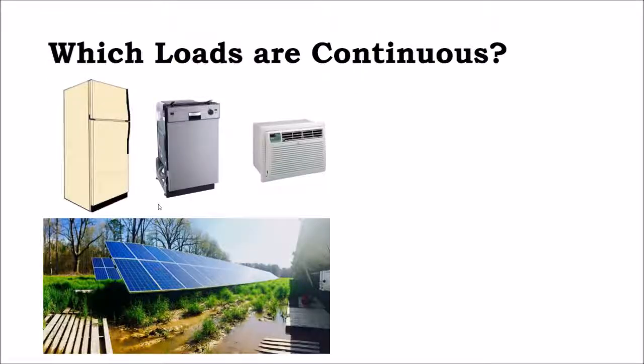And so for non-continuous loads, you may not have the extra ampacity requirement that continuous loads have. So like with the solar array, you apply an extra 25% because it's a continuous load. And then you might also find yourself applying additional corrective factors. But if you think about it as, okay, is this a continuous load? Yes. Okay, I've applied my 25%. Well, have I adjusted for temperature? No. Okay, well, I still have to do that. You start being able to understand all of the factors that need to go into your calculation.